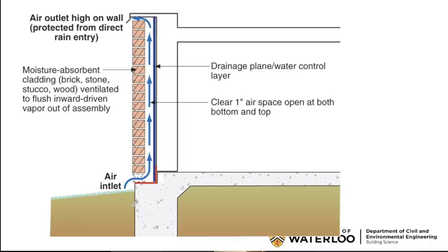So even brick can be ventilated, and you can get clearer spaces in them, but it takes a bit more effort. So you usually do it by having larger cavities. You specify 2-inch, 50 millimeter cavities, and then even with dimensional variations, you still end up with 38. And then you try hard to inspect that they don't clog them up with extra mortar. And people have built these, have measured these, and if you look at buildings around Waterloo, particularly, Cambridge has fewer high-rise brick buildings, but if you look around, you'll see vent openings at the top and drain and vent openings